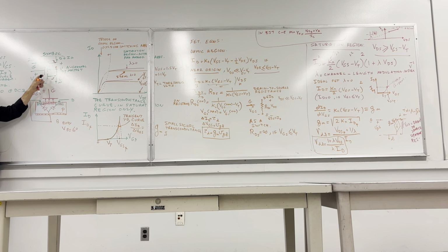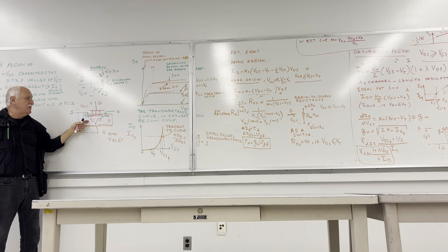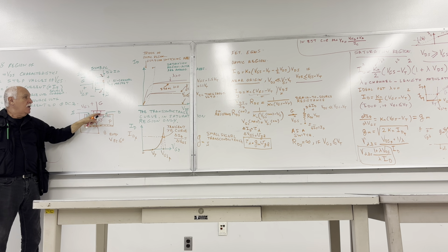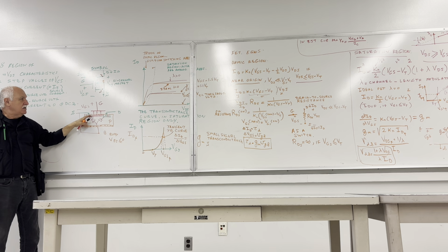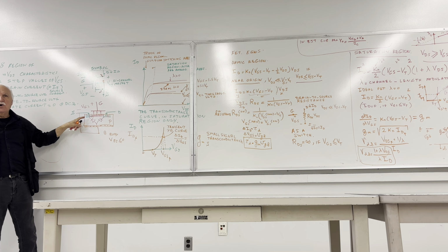Break, okay? If it was a different type of MOSFET, known as depletion mode MOSFET, there would be a layer of N between drain and the source deposited there. So we would have an N type already built.